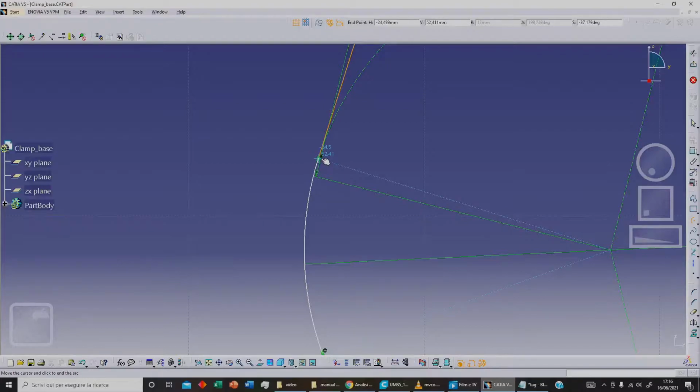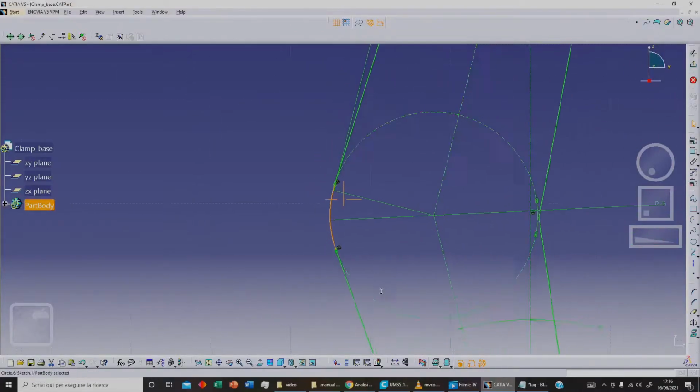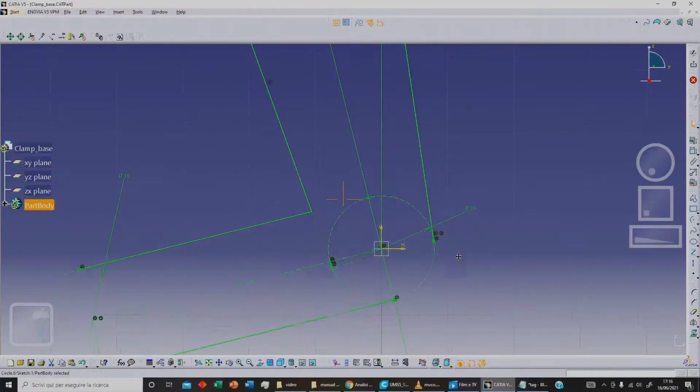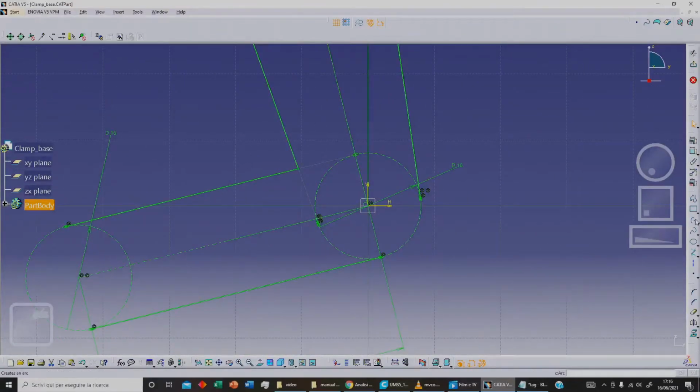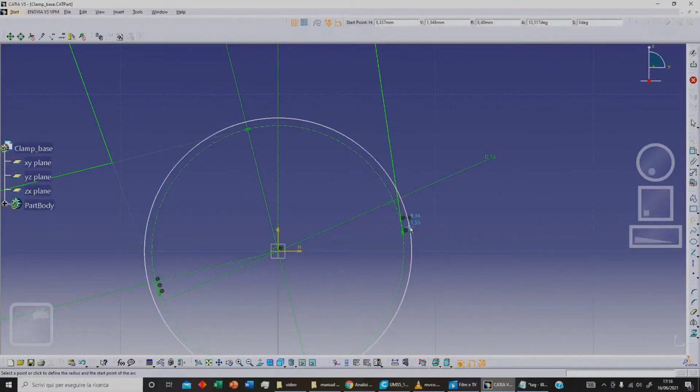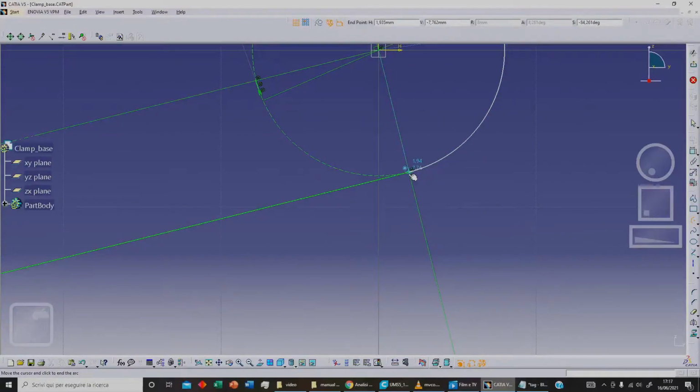Okay. As you can see, we've got difference. We want coincidence between two different points. This is the condition, and let's click on OK. And we need a third arc here, so we can select the origin as our center point, and we can select, for example, this point as our first point, and we want this point as our second point.